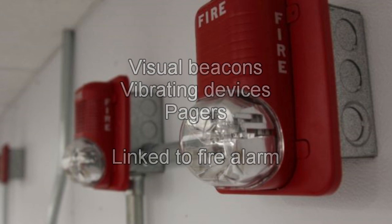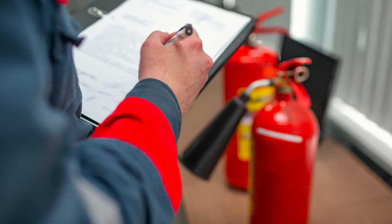The fire detection and warning system should be supervised by a named responsible person, given enough authority and training to manage all aspects of the routine testing and scrutiny of the system. Control and indicating equipment should be checked at least every 24 hours to ensure there are no specific faults. All types of fire warning systems should be tested once a week.